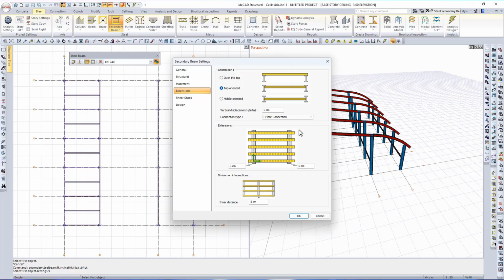The software pre-designed the connection according to the moment and shear capacity of the associated beam section. So, because these default connections are already capacity compliant, the design is automatically safe. If you want to reduce the capacity manually, you can later adjust it through the Connections menu.